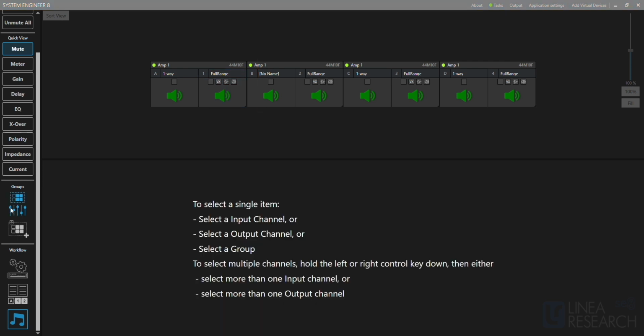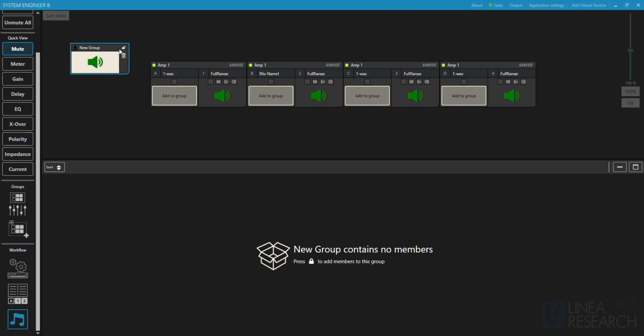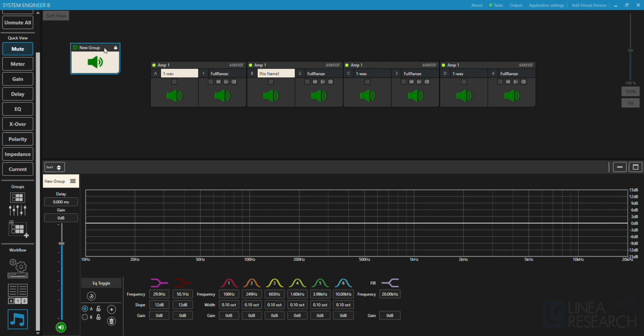Within your tune workflow, we can also now add groups. So to add a group, I can click this add group button here, and that will populate our Explorer view up here. And now to add to this group, we can unlock the padlock here and we can add a couple of things to this group and then lock it back up. Now you'll see that if we click on this new group up here, it will now populate our detailed view down the bottom. We can also name our groups here.